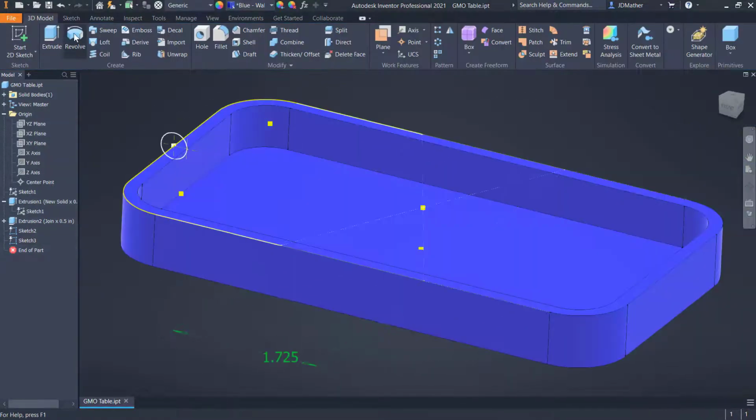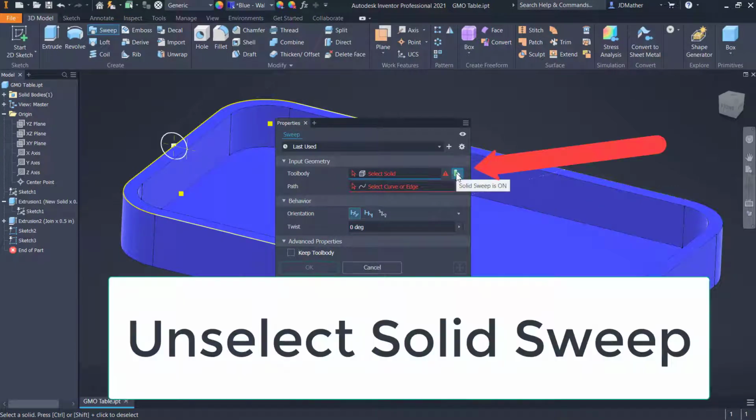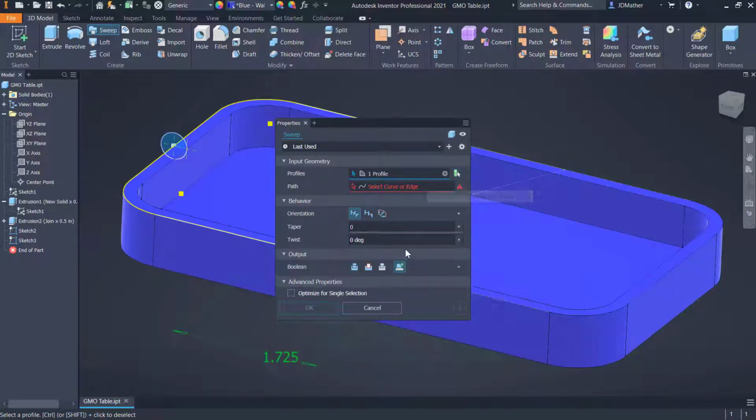I'll then do a sweep, and I want to sweep this circle along this path, but it's not allowing me to select a circle, and this is actually an issue that we'll have to watch out for. The last sweep that I did it as a solid sweep. I don't want to do a solid sweep. I'm going to come down here and tell it new solid, and I want for the curve...